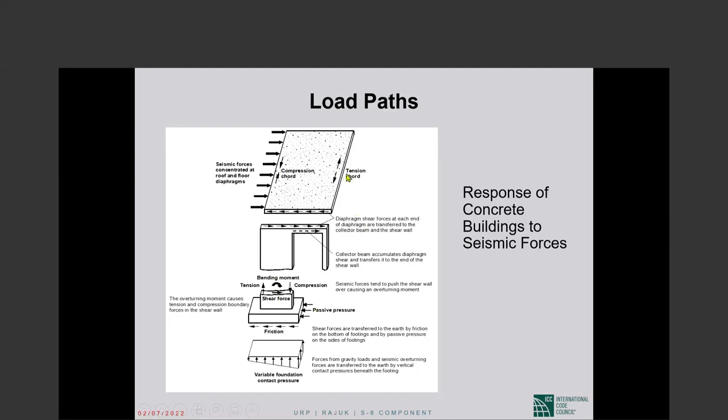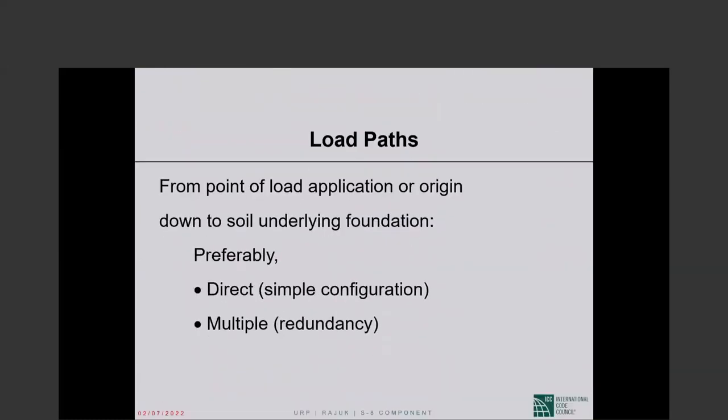Okay, so this picture tells you the concept of the load path. In this case, the inertia forces are going through the diaphragm to the vertical elements of the seismic force resisting system, as we call them, the columns and the shear walls, which take them down to their foundations, and the foundations transfer them to the ground underneath the building. So concept, very important concept of load path. From point of load application or origin down to soil underlying foundation.